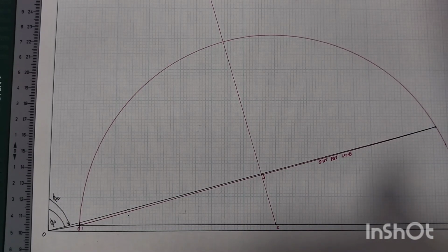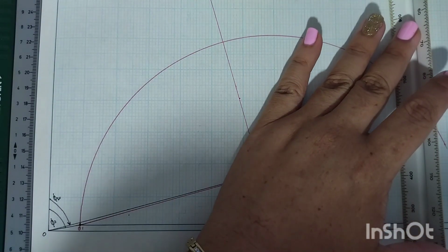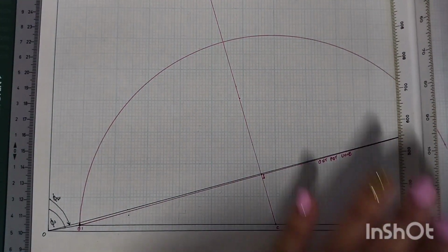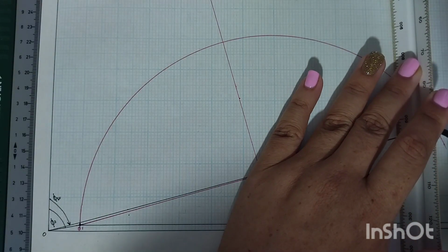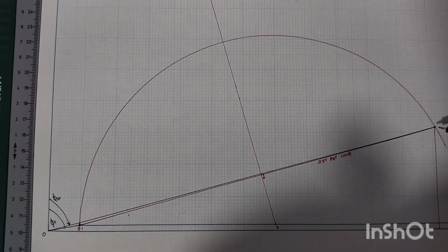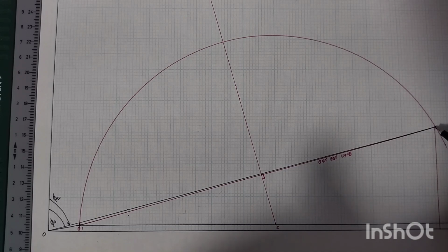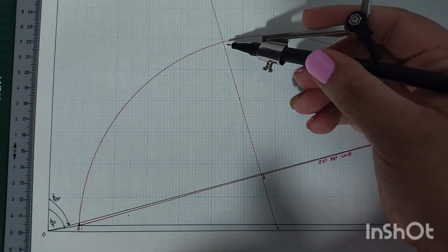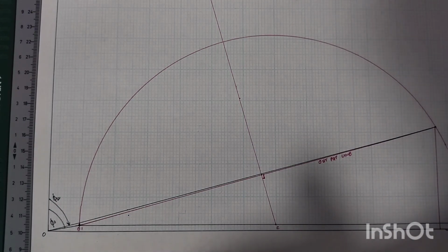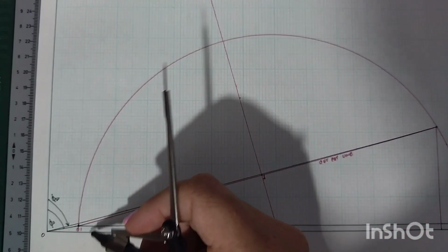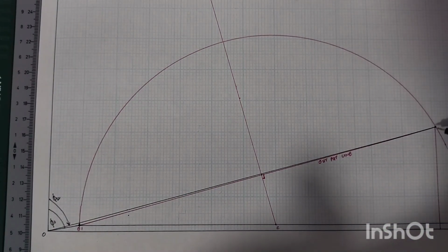So if you construct a line parallel to your vertical axis, straight down to your horizontal axis over there, that line gives you all the information you need at standstill or at starting when your slip is 100%. So in between your new horizontal axis, that is from O prime to the end of that line, and your short circuit adjusted current, that is your stator and the rotor copper losses up to the end over there at standstill.